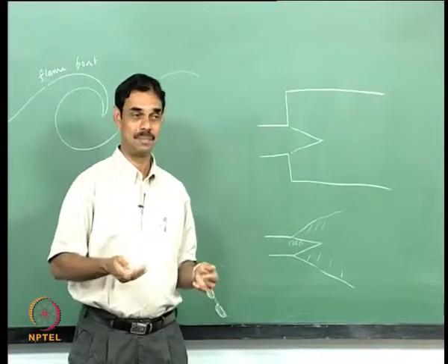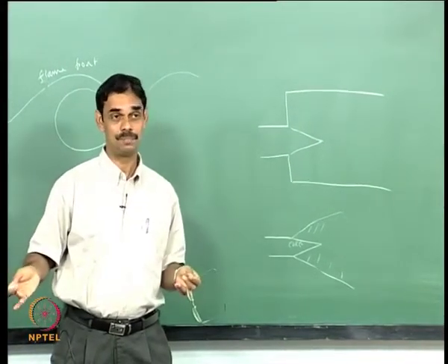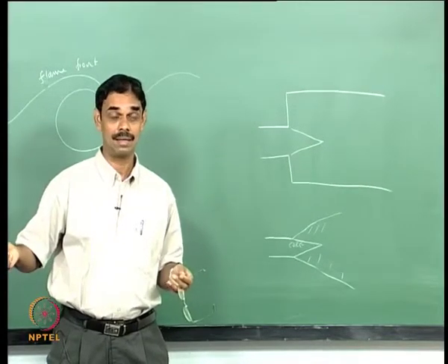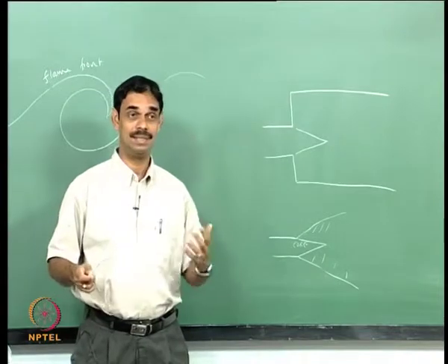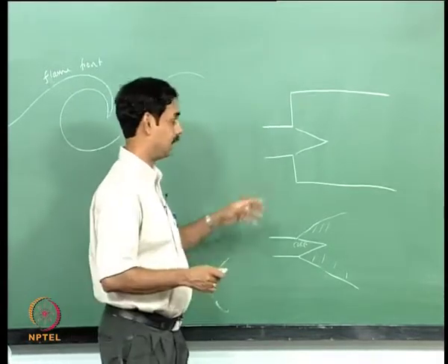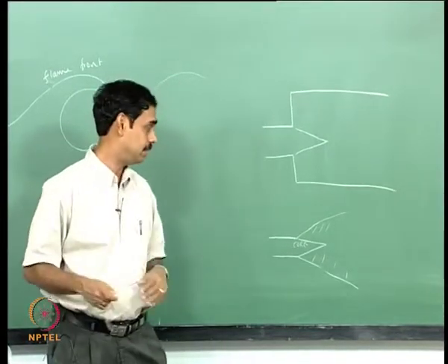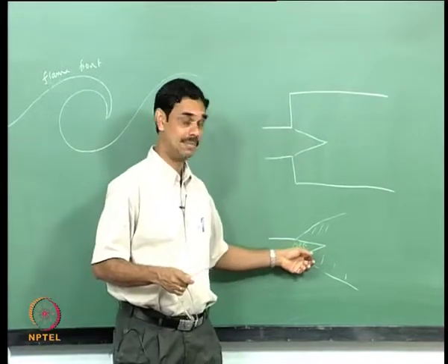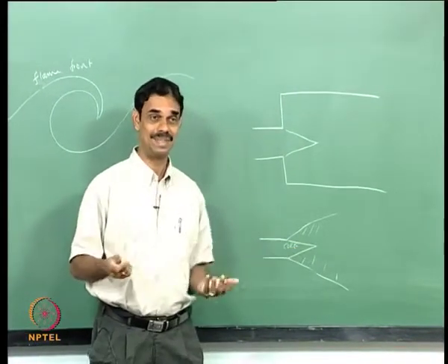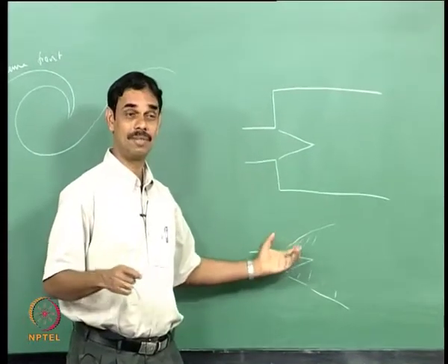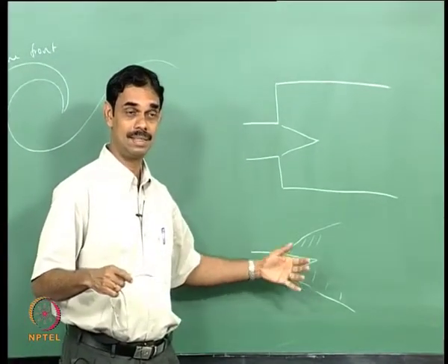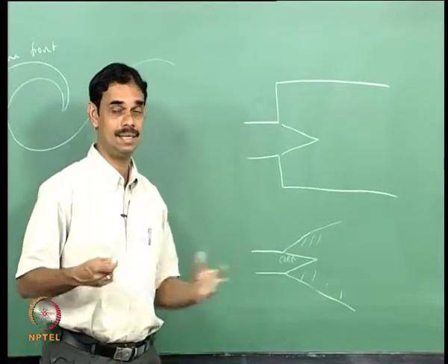Yes, it is possible in a simple Bunsen burner flame or something like that, but not in a real combustor. You would have vortex shedding if it is coming at any serious velocity, and you would have a vortex roll up, and the combustion would be periodic. And if you have a jet, the jet will have vortices. If you time average over a large time you would get this picture, but the instantaneous picture is highly unsteady.